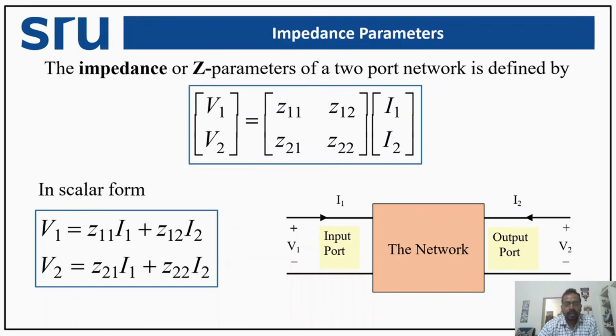This means that whether you connect a load, a source, or another circuit to the port, the Z parameters do not change. This property makes the parameter model extremely useful. Once we determine the Z parameters of the network, we can use them in many different analyses. We can develop an equivalent network, and this equivalent network behaves similarly to the actual subnetwork.